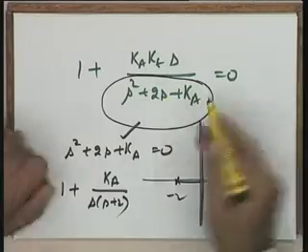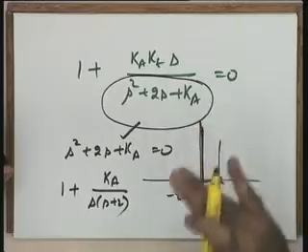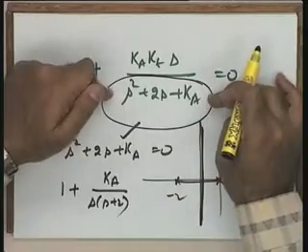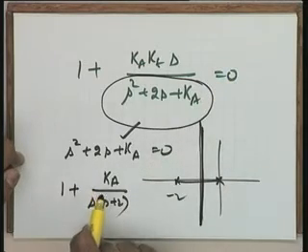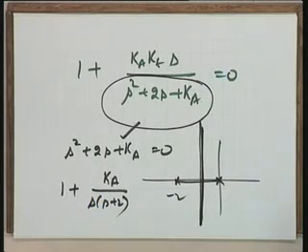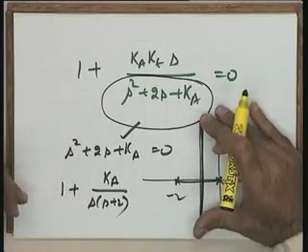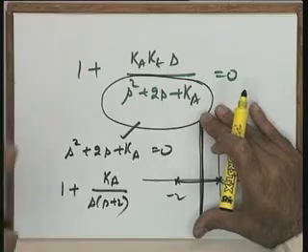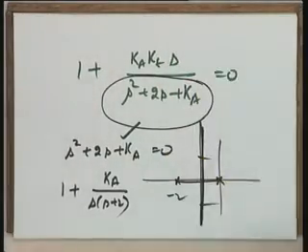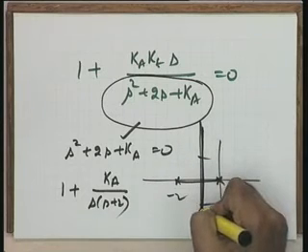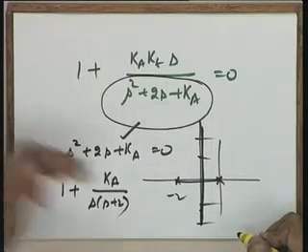But suppose this denominator itself is a complex function and there is only one parameter. So first of all you can get the roots of this complex function with respect to the change of that parameter by studying this equation and transforming it into the format of a root locus equation, and this is the root locus branch. Now once you have got this, this particular root locus gives you actually the open loop poles for the complete function, and then you go back to this, you take any 2 points of this, taking these as the open loop poles, you draw the total root locus branch. Take these 2 points, taking these as the open loop poles, you draw the two root locus.